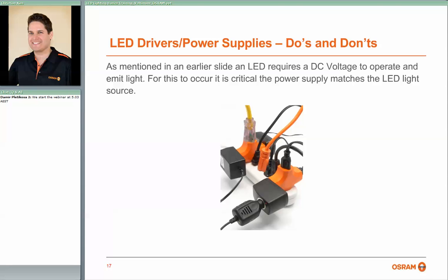Because if we're talking about the relative and the absolute photometry, we're just talking about the total light output, so that's not factoring in the angle or anything. That's just the total light output of the luminaire that I was referring to there. If we're talking about a specific angle, again, we'd probably be measuring candelas for the light source to measure some intensities, if that's something that's important for a spotlight, for example.